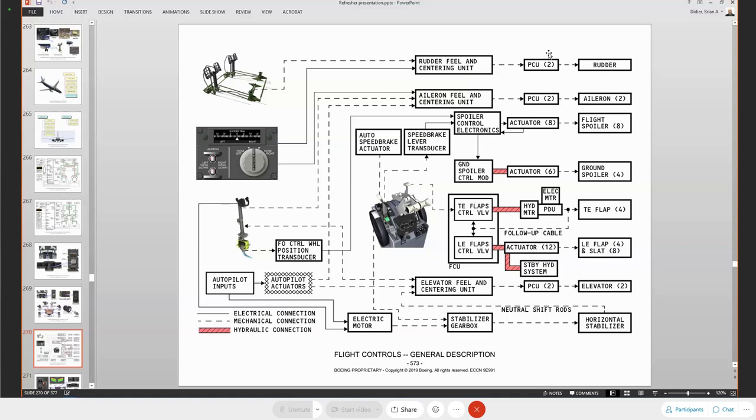Okay. And that happens on the MAX also. The difference between the MAX and the NG, however, is the FSEU is going to, which controls that limiting. If I lose either engine on the MAX, either the left engine or the right engine, it's going to remove that limitation and put full hydraulic pressure back available to the PSEU for the rudders, okay, to help control it.